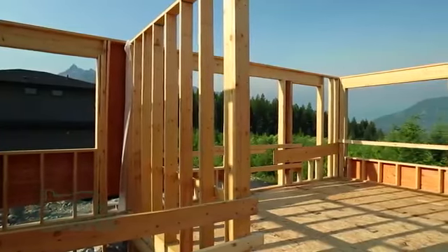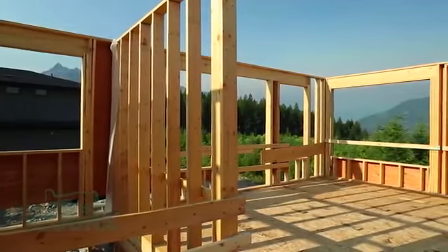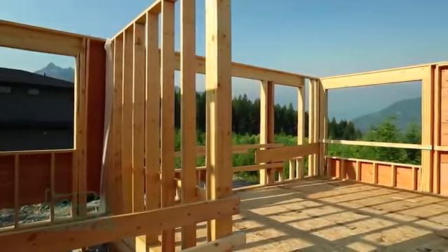So some of the most common types of fall protection that framers can use to help keep their employees safe: I'm seeing a lot more guardrails being installed on walls before they're stood, so that as soon as they're stood, as they're framing that next floor in, they already have that guardrail in place. That's a lot quicker than setting up anchors in some cases, and it provides a really good visual barrier as well. I've seen a lot of them using fall restraint, simply because if you're working off of a floor, the idea is that you don't want to get to the point where you fall out, right?